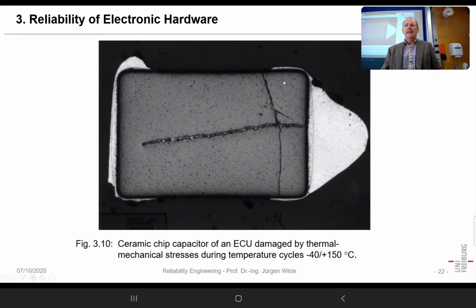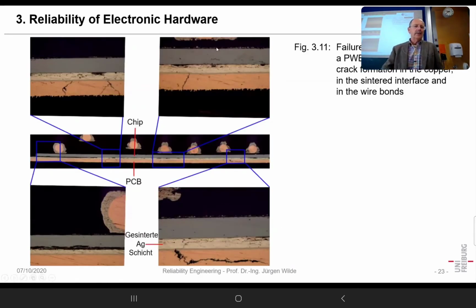And what is also not liked very much by these devices is, for instance, very high cooling rates. So that soldering also has a certain effect. In the end, they do not really fail. Unfortunately, they tend to fail when the board is with the customer and when it's in operation. That was another thing also for power semiconductors.